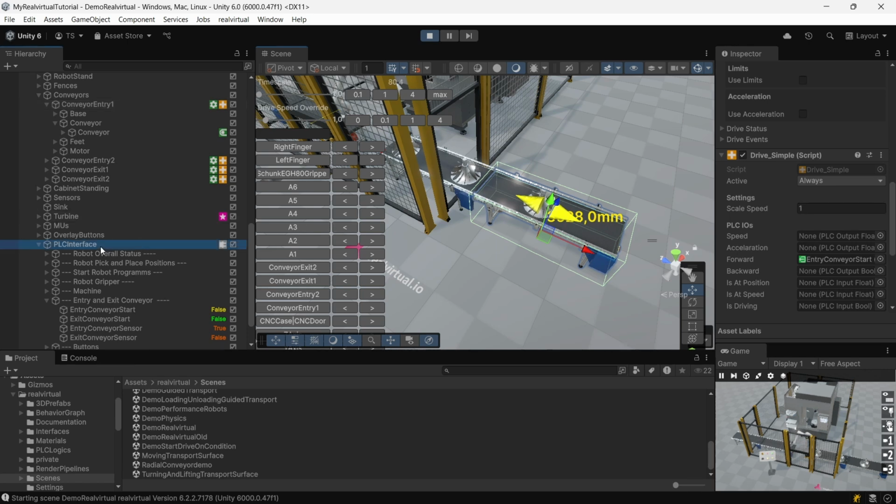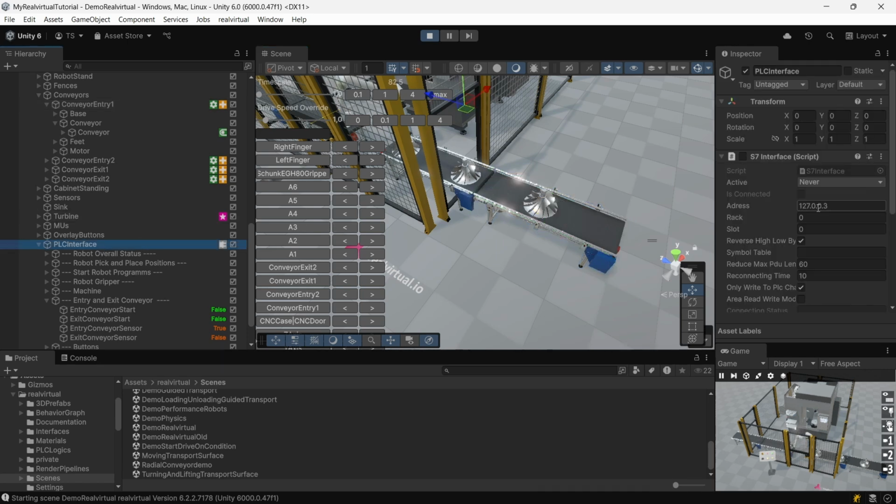All signals are usually, if you are using it for virtual commissioning, underneath a PLC interface. In this example, it's an S7 interface. It's deactivated for the demonstration cell because we assume that you don't have a ready-to-run Siemens PLC on your table. But if you have got it, you could connect it.